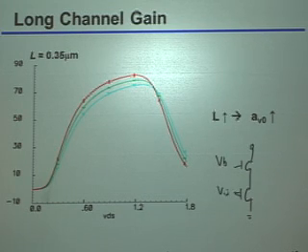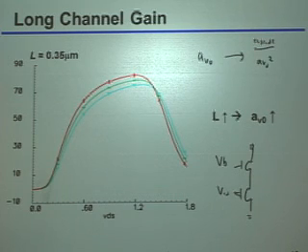Okay, so let's say that it would look something like this, where that VB is just some fixed bias voltage. So if your original device gave you an Av0 of gain, roughly speaking, what would the Cascode give you? Yeah, roughly speaking, it gives you something like Av0 squared. Now, obviously, the penalty is that you probably need more drain to source voltage to actually get that full Av0 squared.